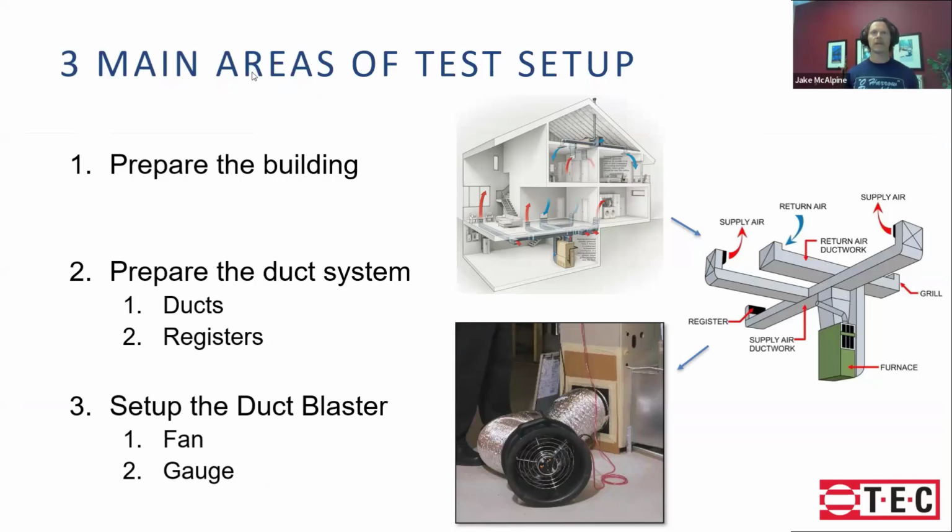Okay. So the way I approach duct leakage is I kind of try to break it down. It is more setup than a blower door test. That's kind of the background that I came from. So I like to break this down and kind of think about preparing the building itself for the test, stepping over to the duct system. Two main elements there are the ducts themselves and also the registers.